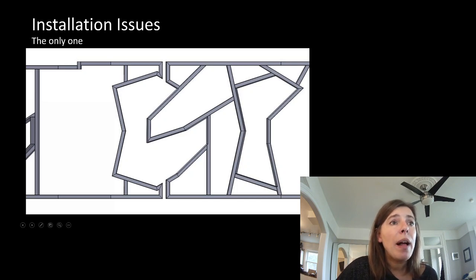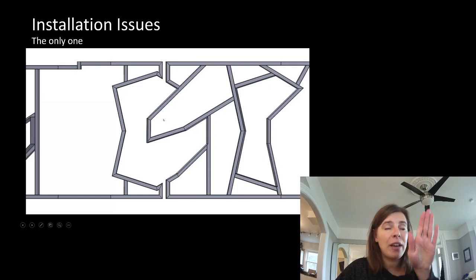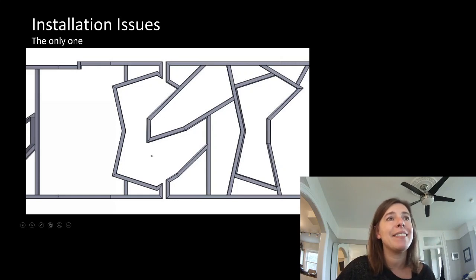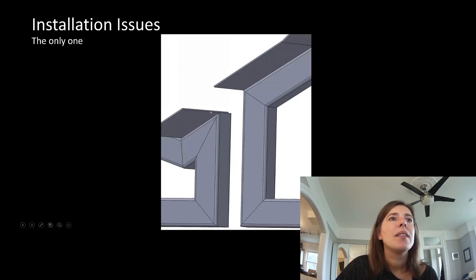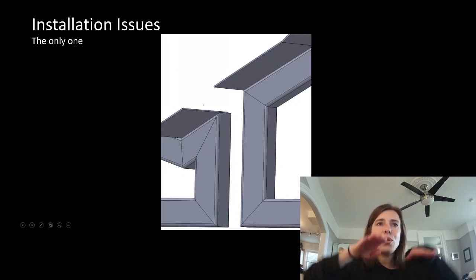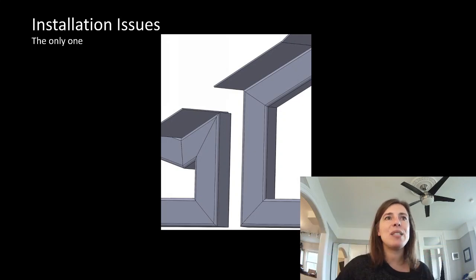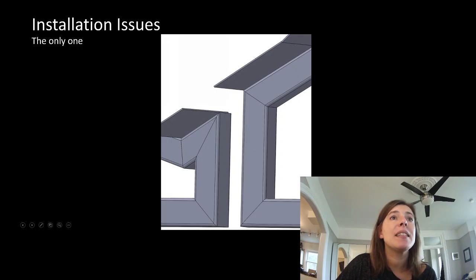You can see it really well in this image here. You can see you're looking straight on at the edge of the panel, but because this is where a facet line happens, and this needs to be flush with this HSS, and this needs to be flush with this HSS, you can see that it looks like that steel slopes in. You can see this is the point. You can see that those two things are on different planes from each other. And that was okay. All that mattered was that this face edge of that steel panel be a perfectly flush line.